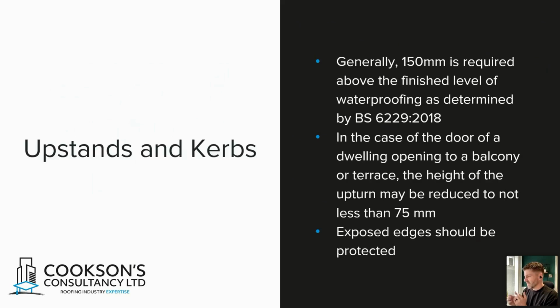And like it says there, exposed edges of the waterproofing should be protected with a flashing or a cover strip or something like that, so we're not bonding the waterproofing to an upstand and then leaving it exposed so water can get down the back. So flashing details and things like that we'll have a look at.